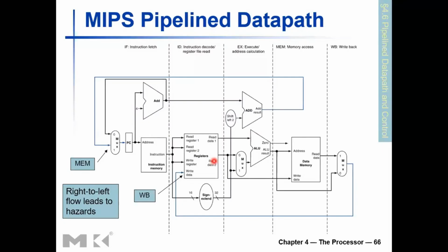So how would the control signals work in this scenario? Or how would the values that you have read from the register file be available for the computation correctly in the execution stage? Because now we are reading another set of operands from the register file right afterwards. You can imagine a lot of structural data as well as control hazards will be introduced that we have not talked about so far, because of this pipeline nature, parallel execution.